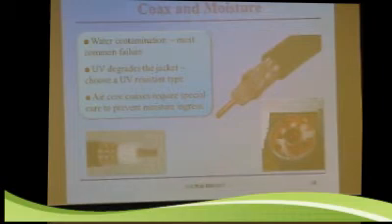Actually, at places like WRAL, they use nitrogen overpressure. They literally pressurize it with nitrogen to keep out the moisture. So that's what the big boys do, but they've got money. So you have to have other ways of sealing it. But even sealing it sometimes doesn't work, because if you seal it and it has a certain amount of moisture in the air, it will condense on the inside after it's sealed. So not even sealing it well is always the answer. Moisture is something you've got to really work at to try to overcome.